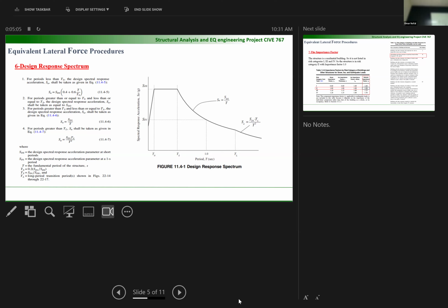So think with me, long periods that mean your building is maybe very, very flexible. Either it's tall and makes long motion. So tall buildings, like the buildings that we are dealing with in our project, it's like 5 seconds to breathe, okay? But if you have a 10-story, it's gonna be maybe 1 second. If they have a 2-story building, 0.1 second to make this motion. Almost very, very small period. So long periods have different calculations.